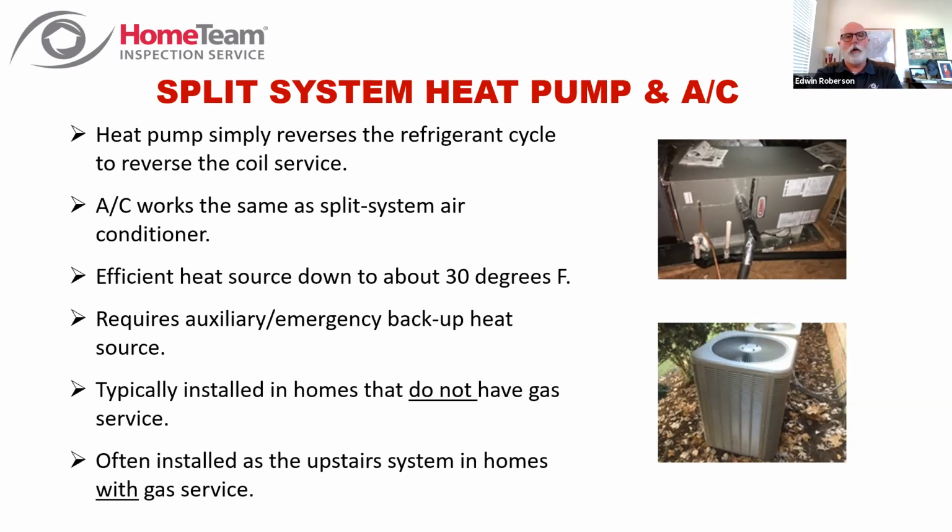But they're also very often installed upstairs in larger homes that may have a gas furnace downstairs. And the reason for that is when you're heating that downstairs area already, that heat's rising. So you don't have that much heat loading requirement upstairs. And so the heat pump that's conditioning the upstairs space just doesn't have to do that much because the space below it is already heated.